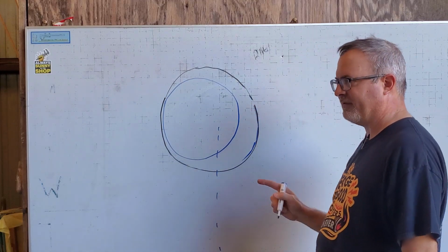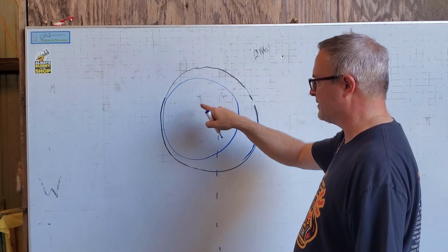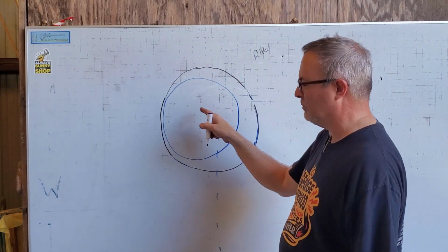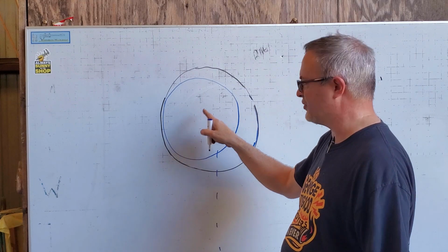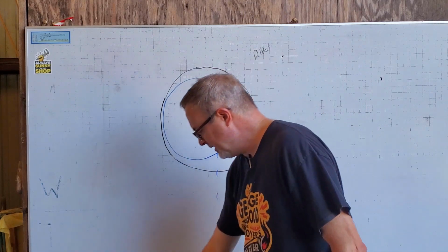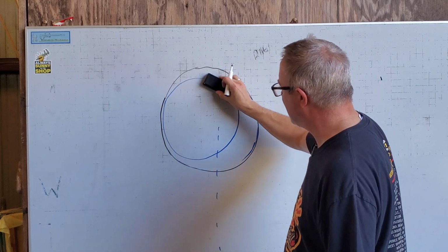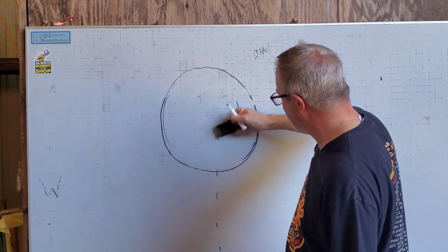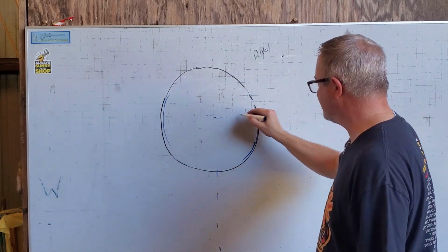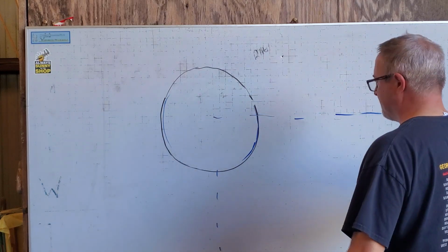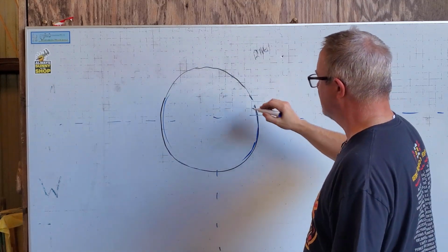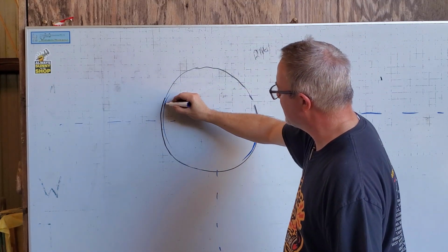And the cushioning effect that they're talking about is basically what's happening here at the end of the cylinder. But at the 90-degree position, when this crank swaps sides, there's no cushioning. If we were to allow this piston to come all the way around to the front of its travel, and everything's in line, the crank pin would be back here.